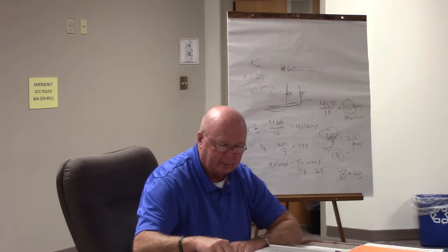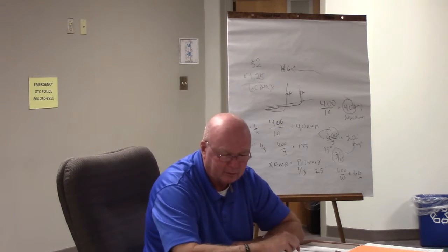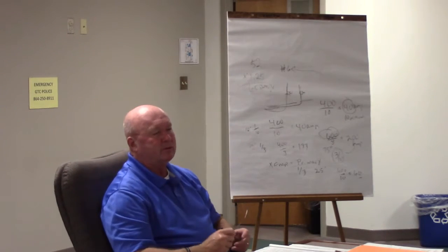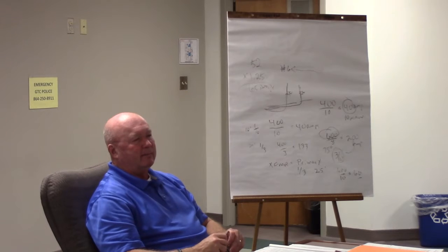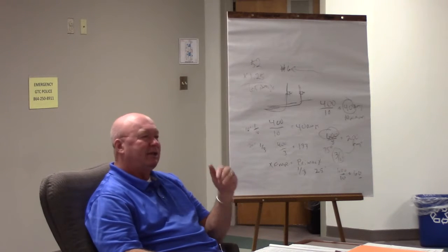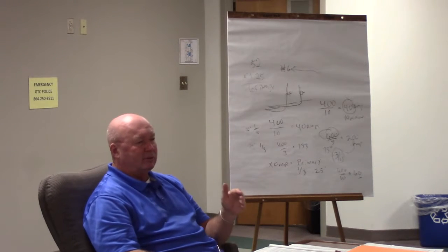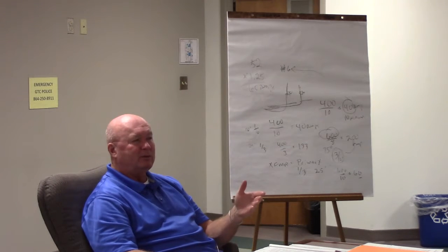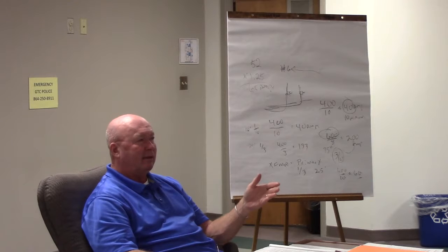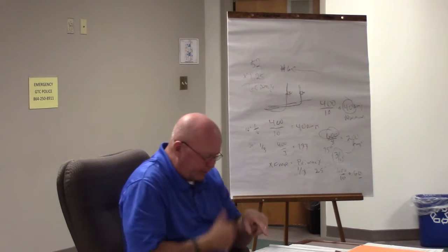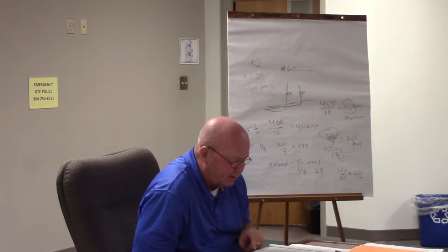220.82, just some optional ways of doing stuff as far as dwelling. You know, there's standard ways of calculating loads, and there's optional ways. Optional way is the easier way. It's only like a 2-step process. A regular standard dwelling calculation is like 7 steps. Optional is only 2, if y'all remember that from the other class. It was much easier. But as far as taking the test, you can't do optional unless they tell you can do optional. And that's what the rest of those right there deal with, optional method.